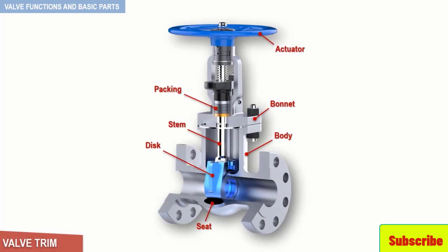The internal elements of a valve are collectively referred to as valve trim. The trim typically includes a disc, a seat, a stem, and, when applicable, a sleeve needed to guide the stem. The performance of a valve is determined by the disc and seat interface and the relation of the disc position to the seat. Because of the trim, basic motions and flow control are possible.